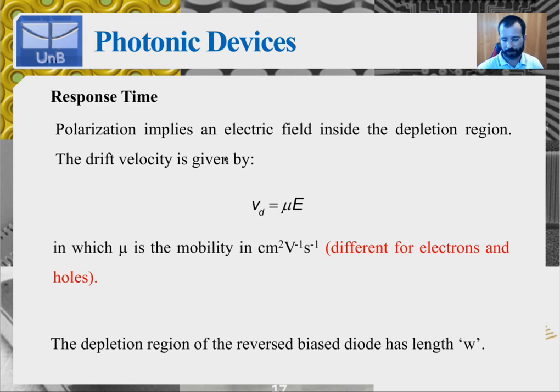So if we're talking about a typical PN junction, just to make things a little bit easier, we have the P and N semiconductors and the immobile ions, which, let's recall, should be negative on the P-type semiconductor and positive on the N-type semiconductor inside the depletion region.